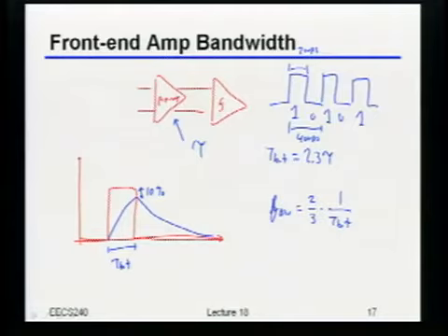Now, by the way, you'll see that if you really work it out for this first phase of the project, you can actually get away with a lot less than this. Just to remind everybody, why would you want to get away with a lot less? It's going to cost you less power, right? So that's one of the things you should be doing in this project: figuring out what gain and what bandwidth I should be using to really minimize the amount of power I have to spend to make this whole thing work. Just be notified that the optimization you come up with, assuming a perfect bit, will not exactly work once the channel itself has some badness in it. But for now, it's actually an interesting thing to work out.